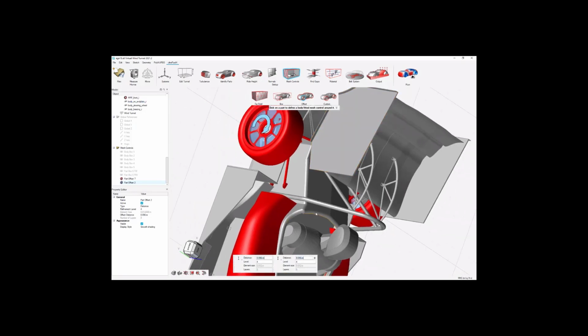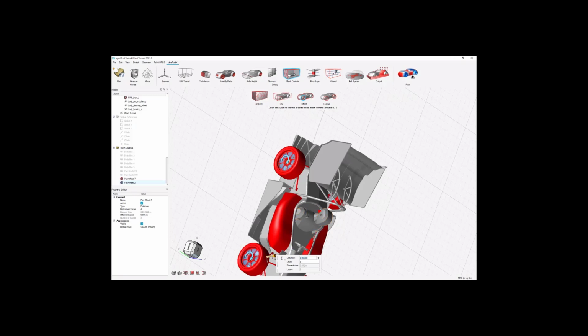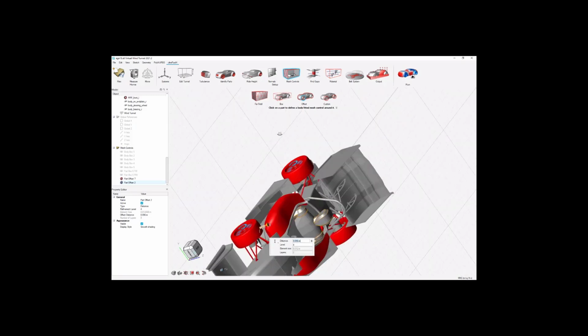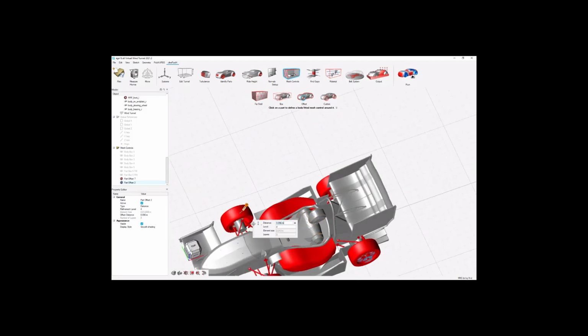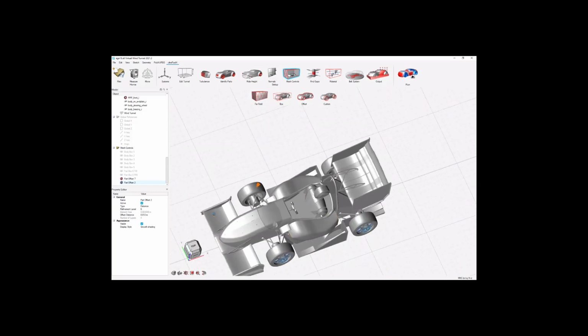Okay, so now that all the parts are selected, we can go ahead and type in the settings. So either you can now end the tool and type it in the property editor like we did before, or you can just specify it here. So this one will be refinement level 6 with a distance of 0.012 meters, which will result in 4 layers. Okay, so that's it.